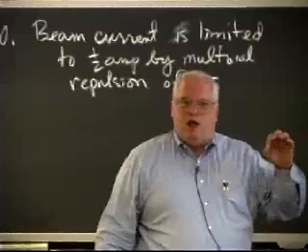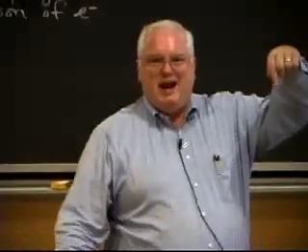If I have a beam current of 1 amp, an electron beam, the electrons will be close enough together that they will actually defocus. You can put them in a magnetic field and squeeze them together to focus them, but as soon as they get out of that field, they have enough repulsion that they will actually defocus.